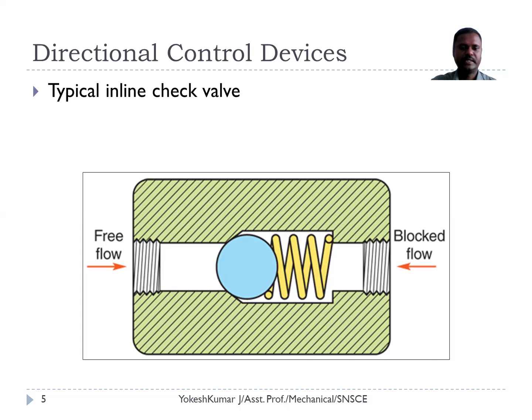Coming to the working, when you allow the flow in the free flow direction, the pressurized fluid enters inside the free flow direction, that is left hand side. Then when the oil pressure exceeds the spring pressure, this ball will slide from left hand side to right hand side, and there will be an opening. So the flow will happen from free flow, that is input to the output, left hand side to